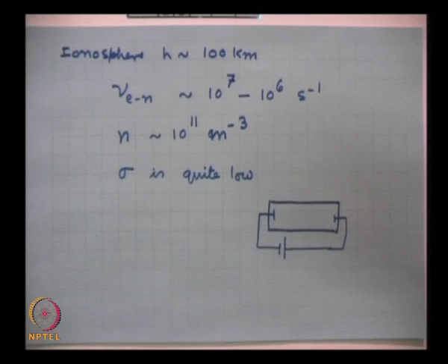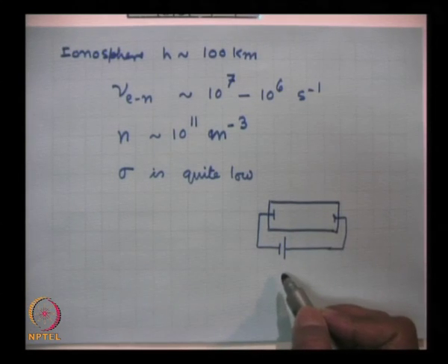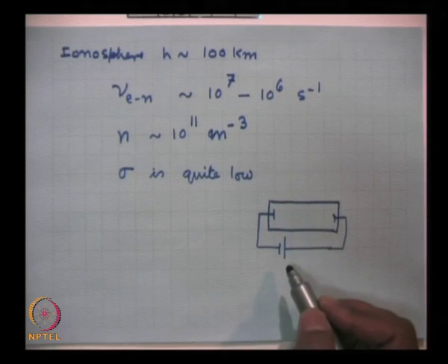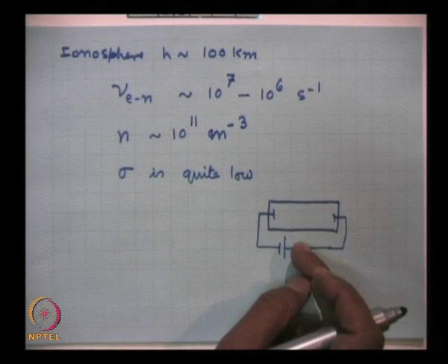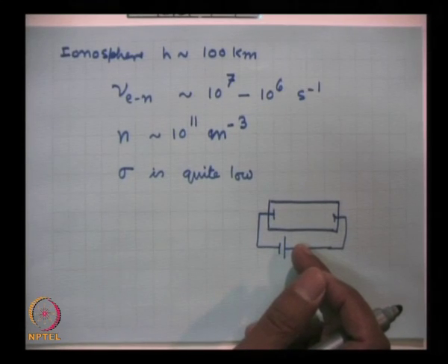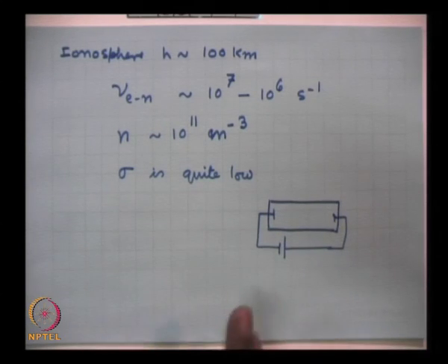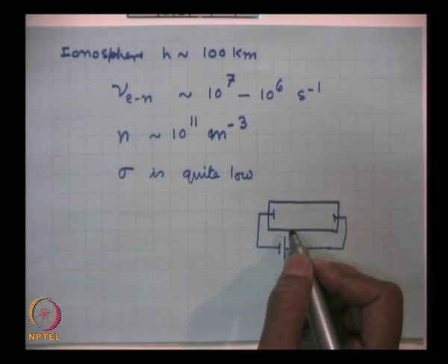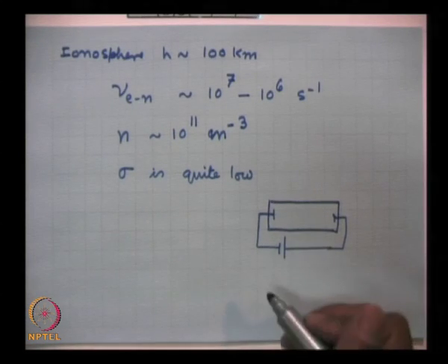Or a semiconductor, if you apply a voltage such that the electric field in this region is of the order of say 1000 volt per centimeter. So, choose a sample of say 1 millimeter thickness and apply 200 volts. This will become 2000 volt per centimeter. So, you can really apply high electric fields in semiconductors if their length or thickness is small. What is happening there?